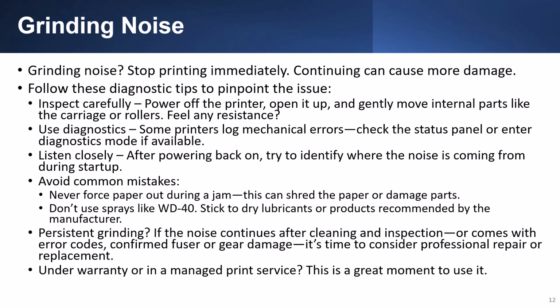Avoid common mistakes. Never force paper out during a jam. This can shred the paper or damage parts. Don't use sprays like WD-40. Stick to dry lubricants or products recommended by the manufacturer. Persistent grinding? If the noise continues after cleaning and inspection, or comes with error codes that confirm fuser or gear damage, it's time to consider professional repair or replacement. Under warranty or in a managed print service, this is a great moment to use it.